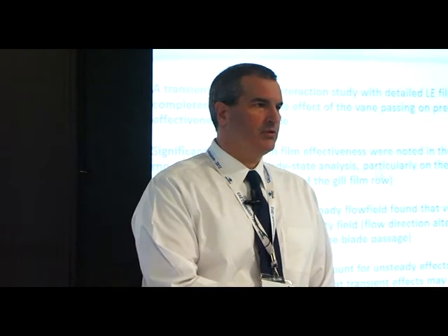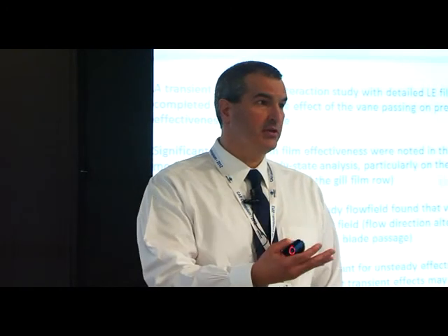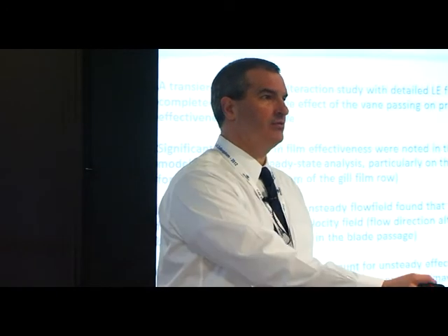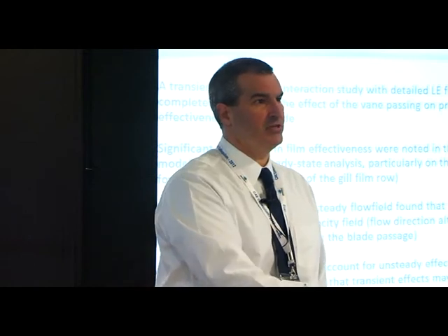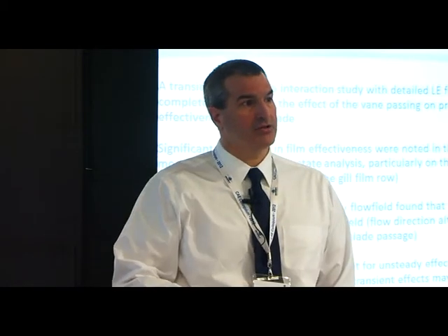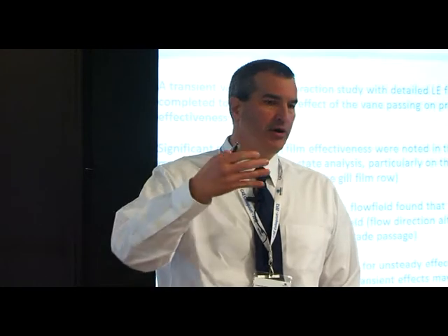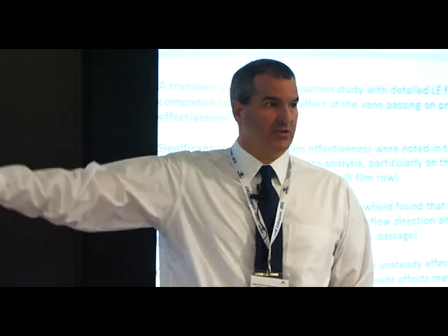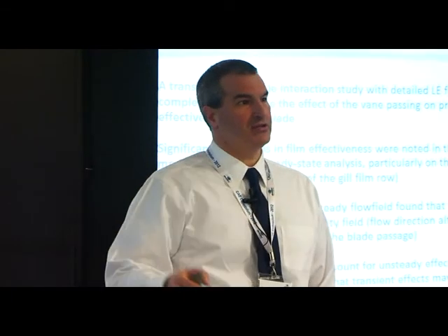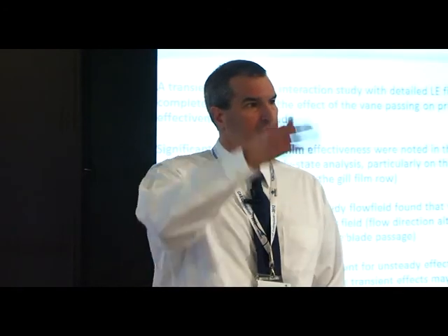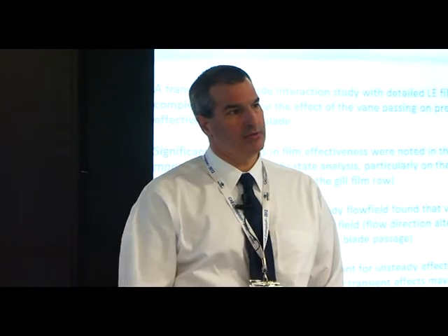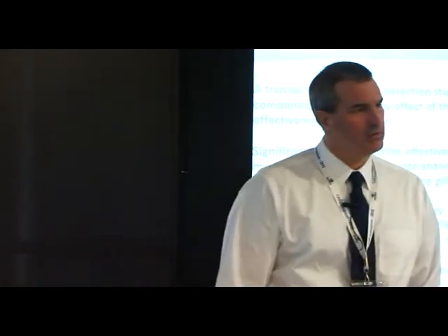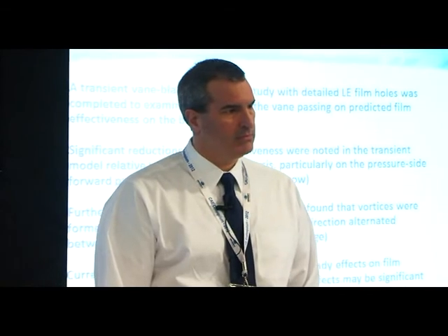Yeah. Historically, we've looked at this and said that the frequency of the unsteadiness we're seeing in the Aero work is so much higher that the structural response time is much slower, and it's not going to see this effect. But we're actively exploring how to connect the Aero and mechanical transient response. Maybe not for this level of detail, but in larger scale things, like cycle changes. As you're ramping up or ramping back down, we're looking at how to couple the CFD and the mechanical analysis.